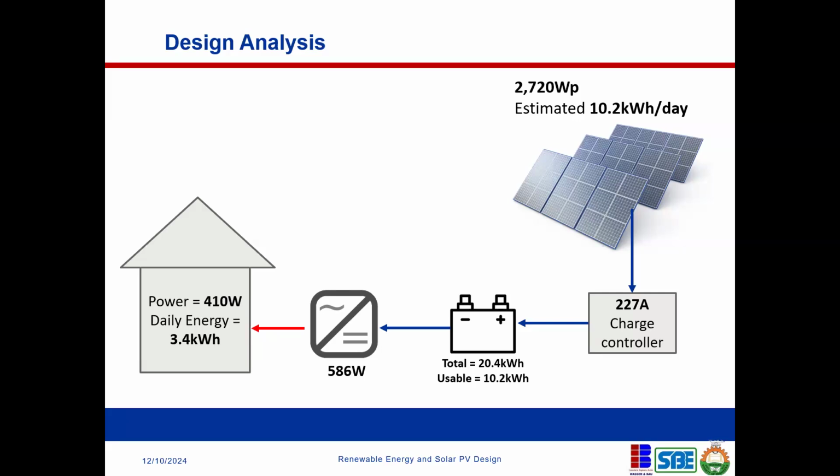Again, you might also ask, why do I need to oversize my solar panel? Because I want 2 days of autonomy. Can we bring in a generator if there is no grid? Is it cheaper? Because the reality is that these 2 days of autonomy can occur, but it's not something that occurs almost on a daily basis. It can occur maybe 2 or 3 times in a year. But you don't want to keep this oversized system because of an occasion that rarely happens. And this happens during rainy seasons, correct? During the dry season, it rarely happens.